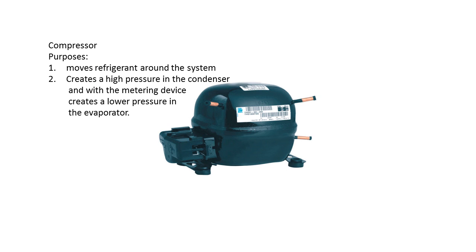The main component of all refrigeration and AC systems is the compressor. Its two functions are to move the refrigerant contained in the refrigeration system around through the various components, and also to create a pressure-temperature difference between the condenser and evaporator. Keep in mind that the descriptions of these following components is very basic and that there is a much more complicated process in play with the refrigeration system.